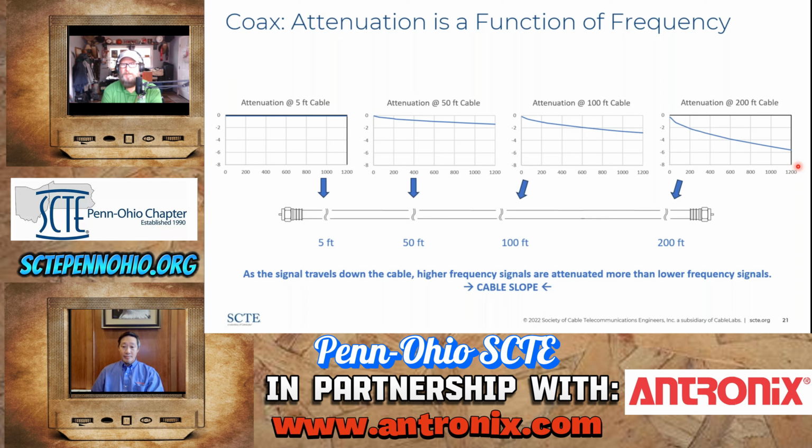And so when we're talking about equalizers, it's really important to understand that there are different types of equalizers, right? There are cable equalizers, which are the inverse of that cable shape, again, not being perfectly linear in its loss to frequency relationship, versus something that's called a linear equalizer, right? Which is, as the name would suggest, linear in its relationship between frequency and loss or equalization. So what we're talking about here is cable equalization to counter the shape of loss through coaxial cables.